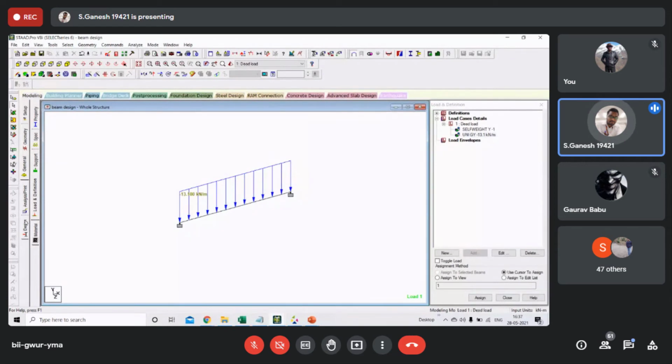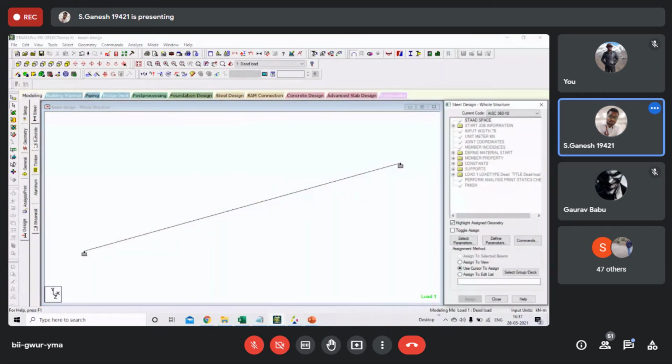So first thing I'll show you that. Click on the design and go to the concrete. I have given the steps in notes, don't worry. And click on your code book, IS 456. For different countries, we have a number of codes. So click on IS 456 for Indian. And then you don't need to click select parameters or define parameters. You can directly go to the command. So I'm just skipping these first two steps.